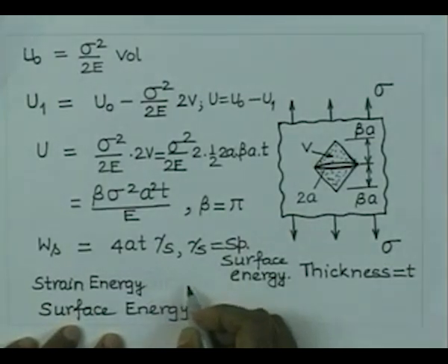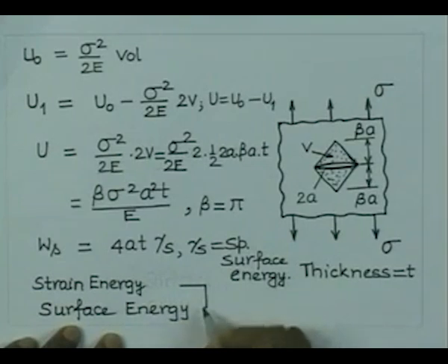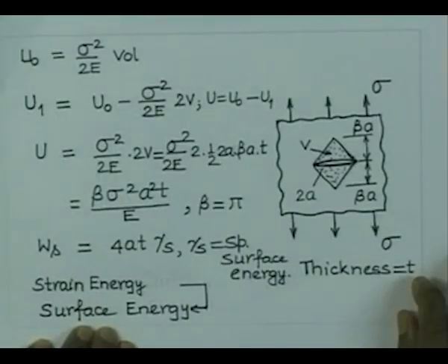and as the crack extends, the strain energy of the body is getting reduced. At the same time, the surface energy of the body is getting increased. Therefore, we can consider that there is a conversion of energy from the strain energy to surface energy during the crack propagation process. So, crack extension is an energy conversion process wherein the strain energy gets converted into surface energy.